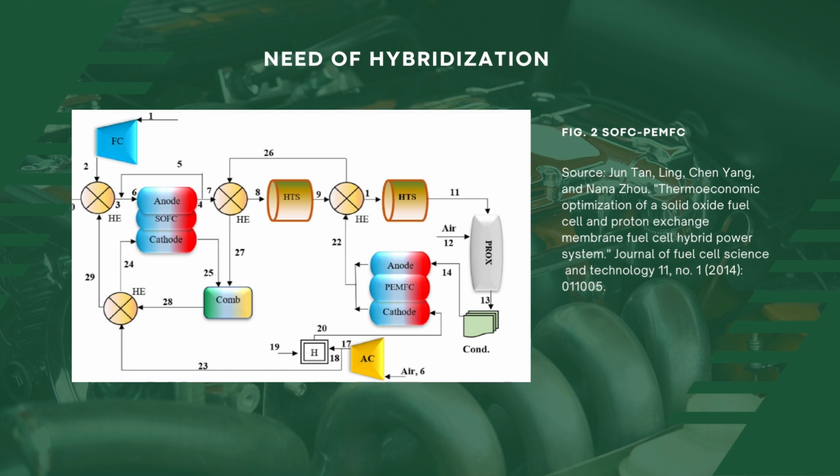Fuel and air are compressed to a desired pressure, pass through a heat exchanger and enter the SOFC stack, cathode and anode side respectively. Recirculating compressed fuel supports the steam reforming reaction. At this point, SOFC creates some electricity, and the remaining fuel can be passed to another application. Here PEMFC is integrated with SOFC to make the system hybrid.